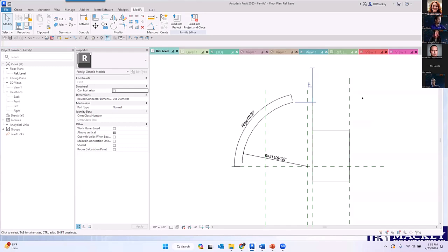I wasn't aware that limitation was there. That's good to know. Thank you. It was there in old versions of Revit, and then they fixed it, and then I think it came back. I went in 23 and tried it, I believe, as well, and it also did not let me do it. My family templates still work, but if you use a new family template, it's broken. So I don't know what that is. I might not be running into it because I'm the same as you and have an older set of family templates.